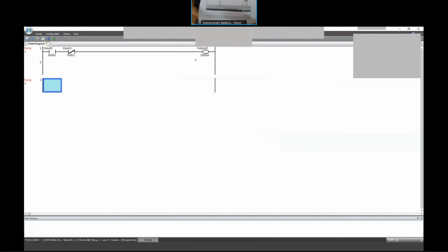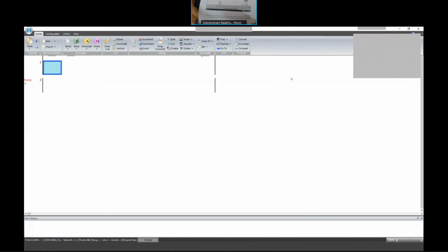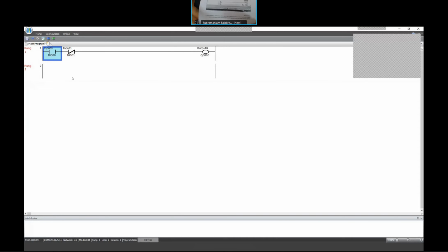So what happened is it automatically is now going to create the first ladder step with the one rung. Move to the next step, and there is one here that can be deleted. Somewhere here there is a delete command. Delete ladder line. Okay, now it looks clean.